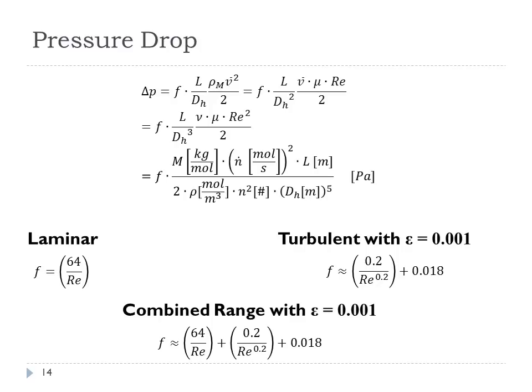The other thing I want to point out is the pressure drop goes like the number of tubes to the -2 power. Right? The more tubes you have, the less pressure drop. Now the more tubes you have, it's probably going to be more costly, right? As far as capital costs. So you can see that there's likely going to be some kind of optimal number of tubes, where if you don't have enough tubes, you're going to have a huge pressure drop, and you've got to pay for that in a compressor. But if you have too many tubes, you're going to end up paying for it in capital costs.